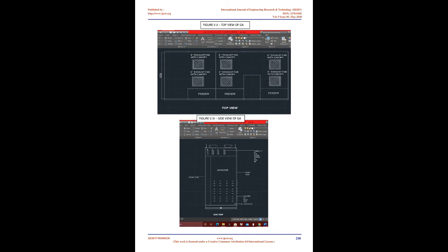For these loads the power factor capacitors can be connected in delta or star. Static capacitors are invariably used for power factor improvement in factories and industries. 2. Synchronous condenser. A synchronous motor takes a leading current when overexcited and therefore behaves as a capacitor. When that category of machine is coupled in parallel with the supply it takes a leading current which partly neutralizes the lagging reactive component of the load. Therefore the power factor is significantly improved.